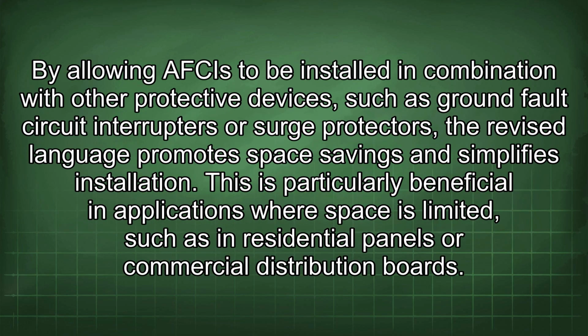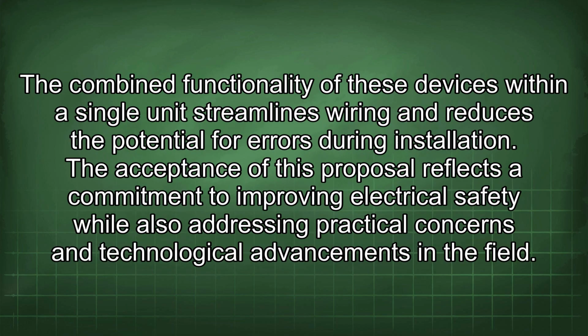By allowing AFCIs to be installed in combination with other protective devices, such as ground fault circuit interrupters or surge protectors, the revised language promotes space savings and simplifies installation. This is particularly beneficial in applications where space is limited, such as in residential panels or commercial distribution boards. The combined functionality of these devices within a single unit streamlines wiring and reduces the potential for errors during installation.